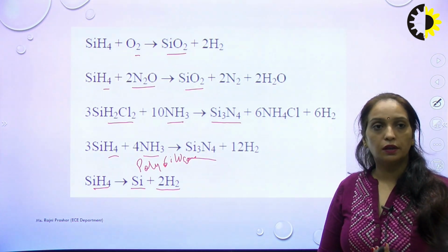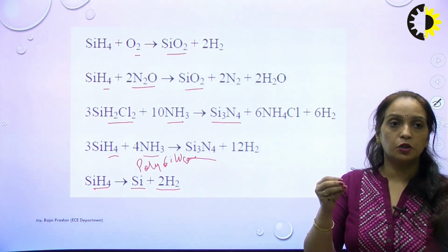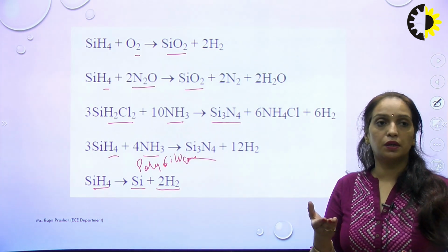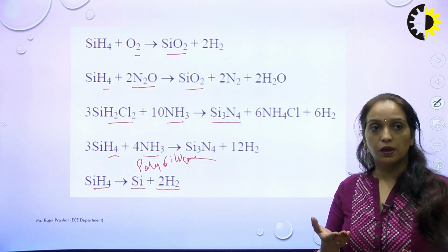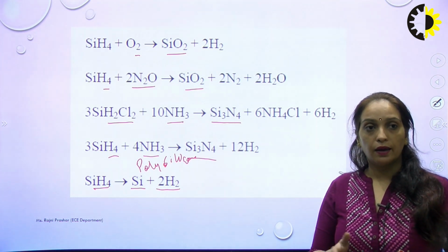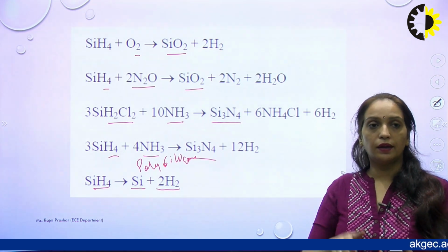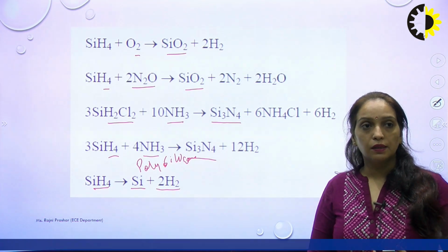Silicon nitride is generally used before the metallization process so that the metal lines do not diffuse into the substrate or get mixed with the substrate. To protect the substrate at higher temperatures and for further processes, we deposit these layers.